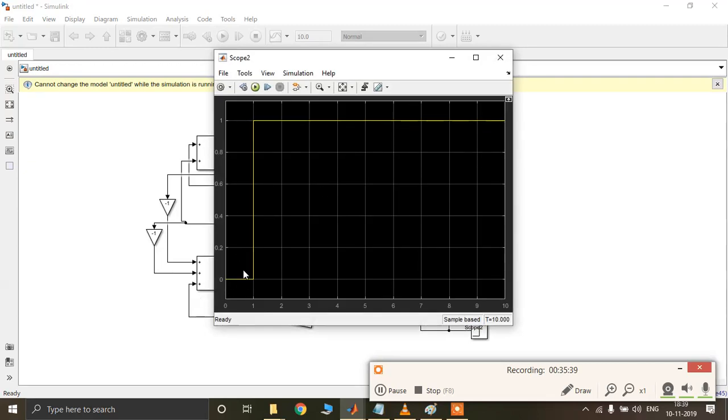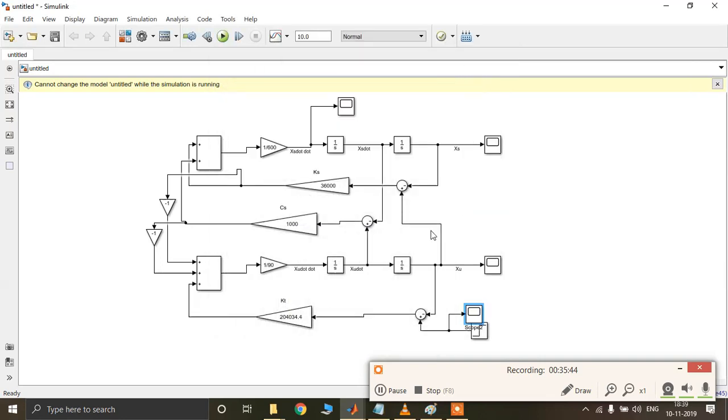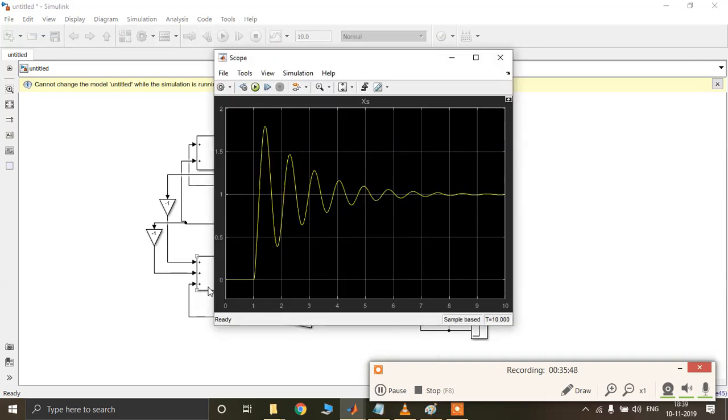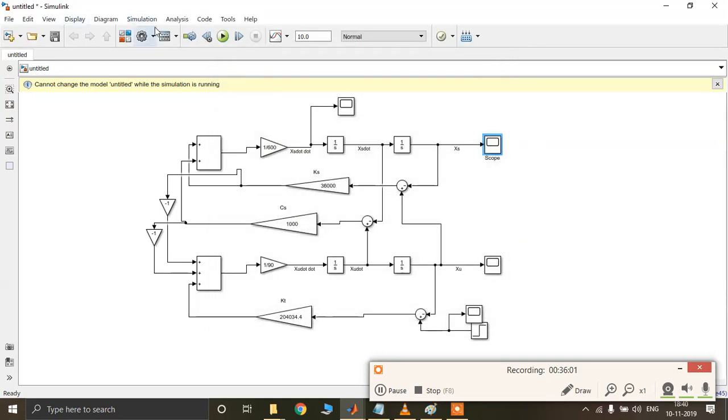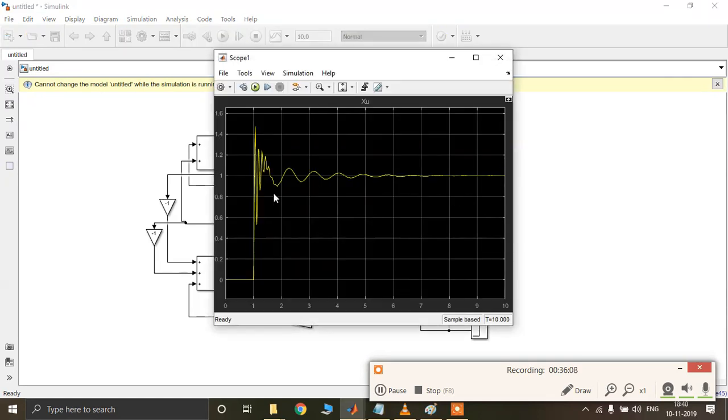Oh, yeah. So at 1 second we have a bump of 1 for 10 seconds. So we first check the axis. Yeah. So at 1 second the car hit the ground. It goes up and it damps out, as you can see how it's damping. You can also extend. There are various functions on it. So that was our sprung mass.